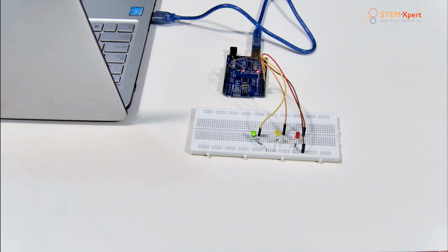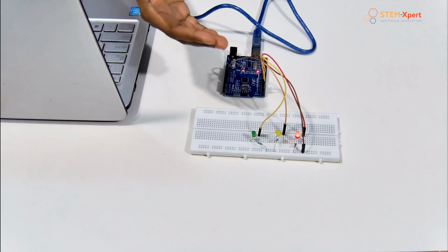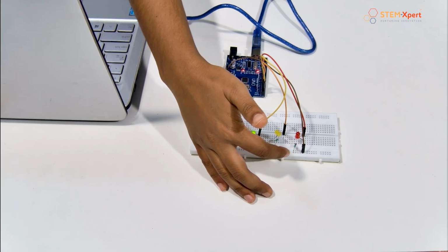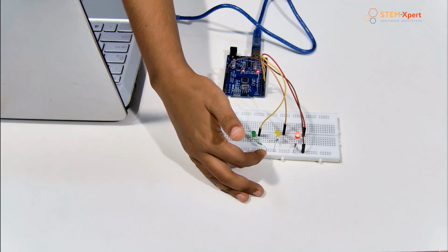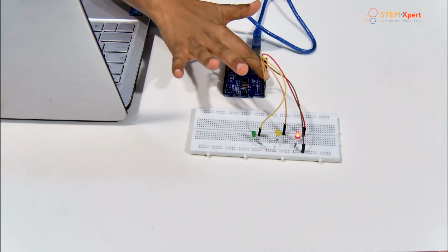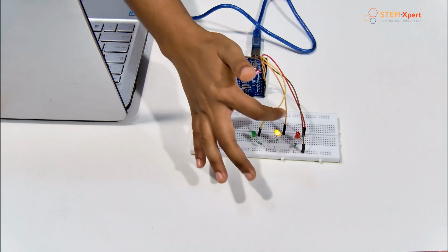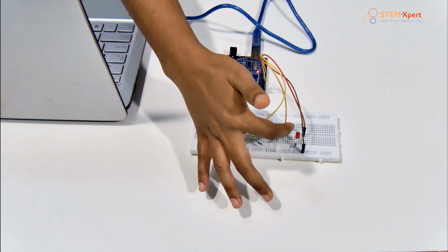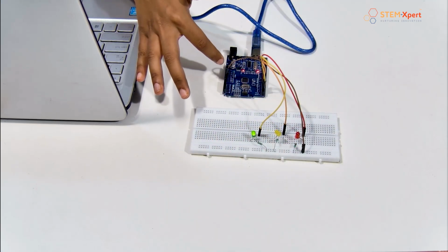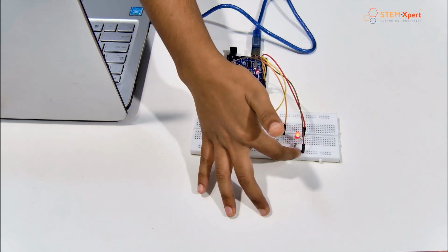Actually, what did we learn in this session? Yeah, we learned the traffic light system project, and we learned the components. We used different types of LEDs for making the traffic light system. We know the colors red, yellow, and green that we are familiar with in traffic on the road, right? Okay. So we have a 330 ohm resistor, orange or brown color, and we connected with this resistor. The positive side of each resistor we connected with the output port of the Uno board using a male to male jumper cable, and each LED's negative terminal we connected with the 3 resistors, and we connected the common ground with the Uno board. Okay, the 3 resistors we connected with this power line, and we connected with the ground pin.